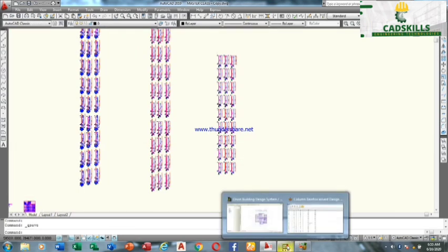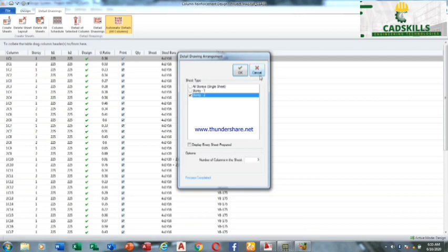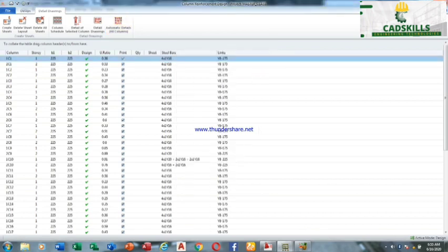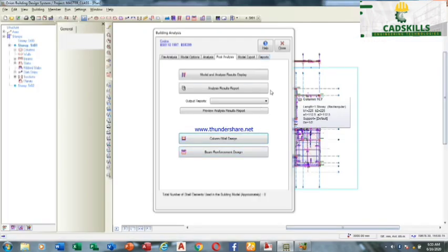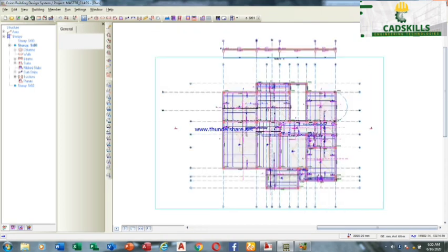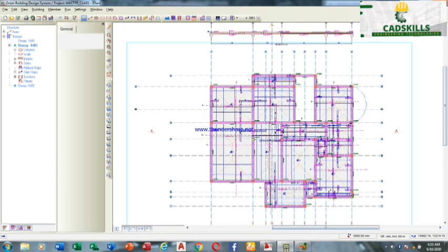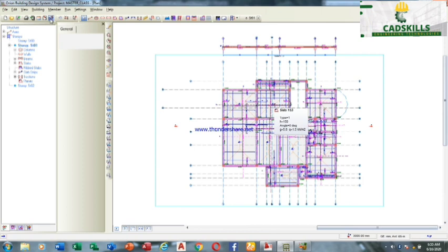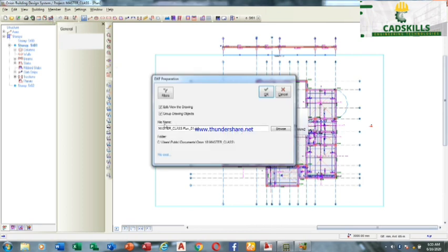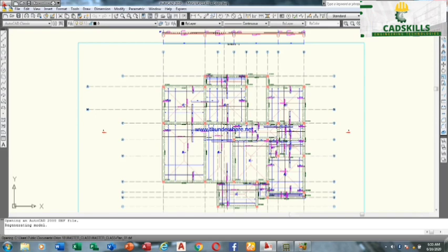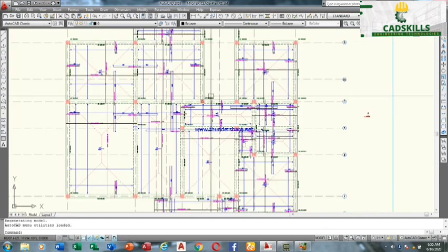Then the next thing we need to do now, I didn't teach us how to export our drawings. Okay, so before I go into foundation, let me quickly do it. So to take this drawing to AutoCAD, you just come here, you click DXF. This is what it's going to save. It's saving in my master class. Okay, now look at it.